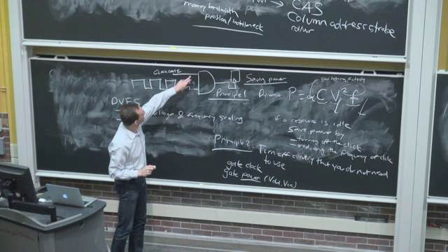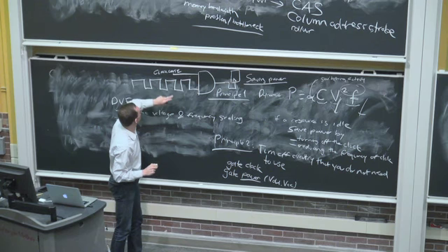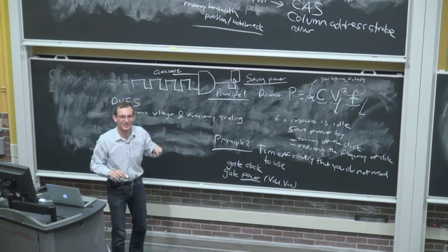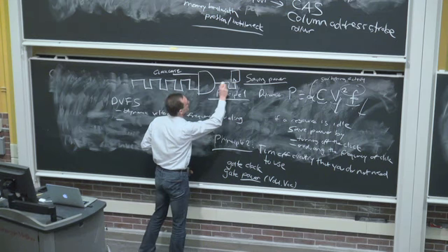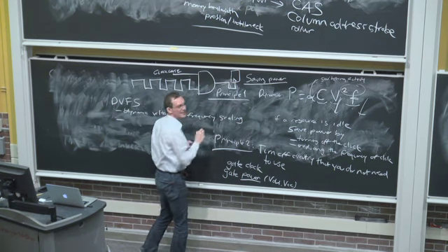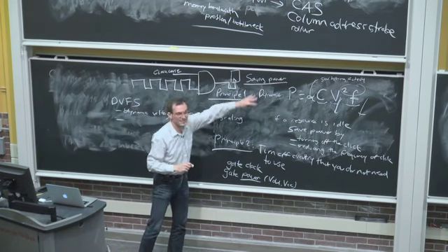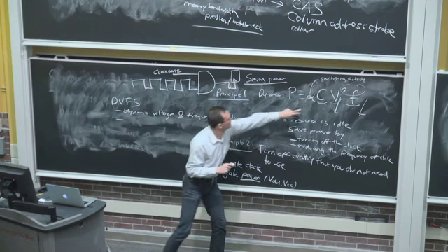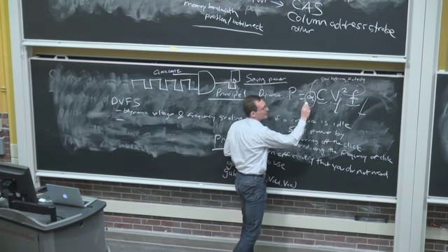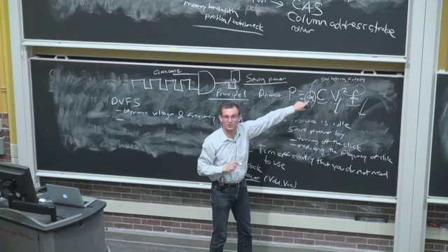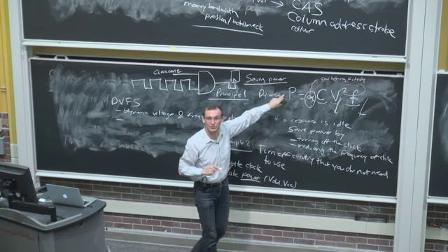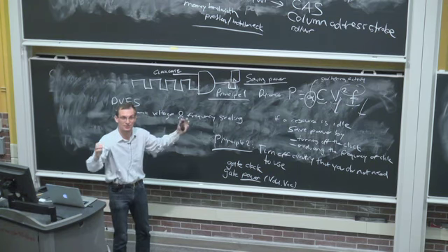And if this clock gate is turned on, well, I guess you could have a clock gate bar or something like that, right? If this clock gate is turned on, you get 0 always out of this, which means that you're not clocked anymore. Which means that your circuit doesn't switch, which means that your activity gets reduced, right? The switching activity goes to 0. So you don't consume dynamic power in that piece of the circuit.